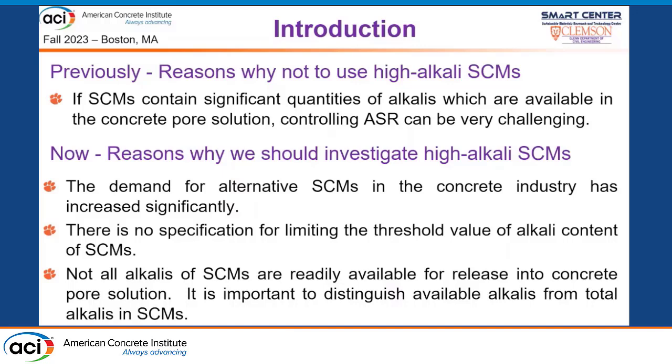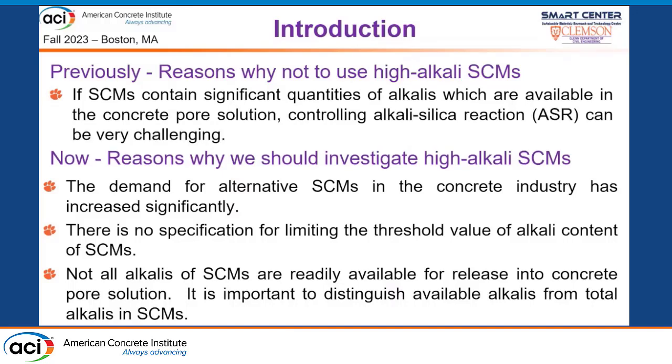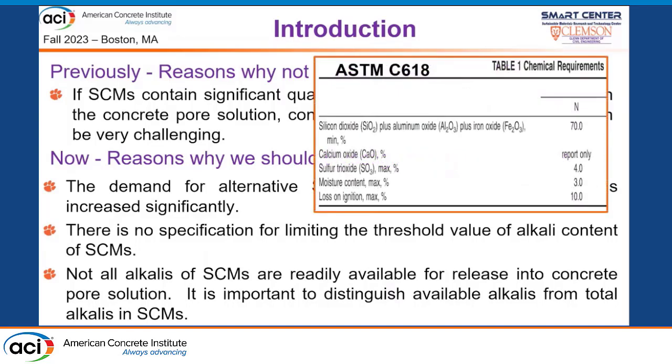Also, there are other research bases for our work. First, there is no specification in the industry for limiting the threshold value of alkali content of SCMs. The primary standard, ASTM C1567, does not give the value. Also, some previous literature reviews indicate that not all alkalis of SCMs are readily available for release into a concrete pore solution.